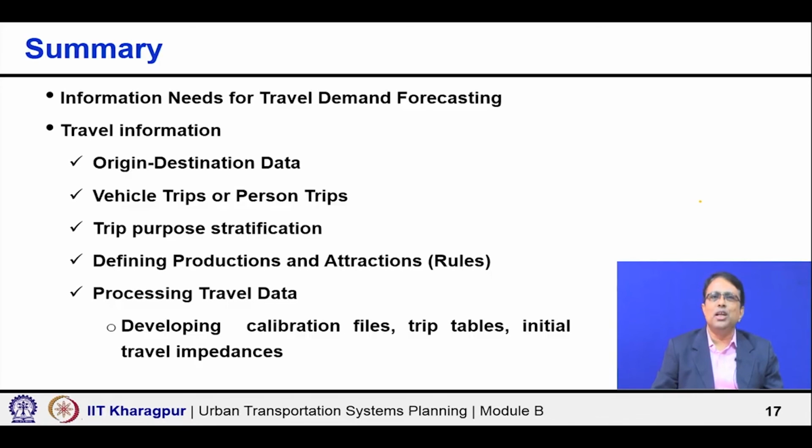Similarly, for trip purpose stratification, we explained the different possible stratifications that one can use, and we said that it is again context specific. Nobody will just tell you, okay, let us do a transportation planning study. They must have some purpose in mind, right. Of course, once you do it, you can probably do many other things, but what is the basic objective of doing this work? Accordingly, you have to select the stratification.